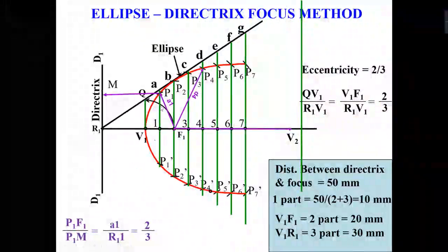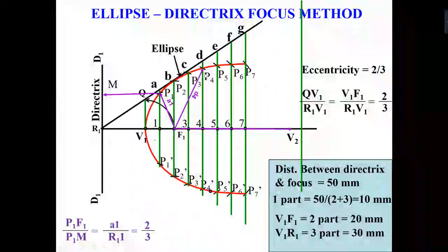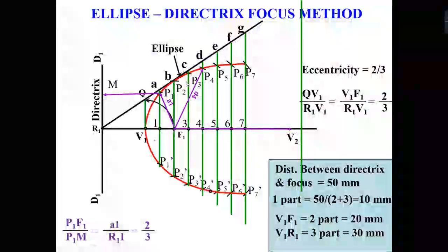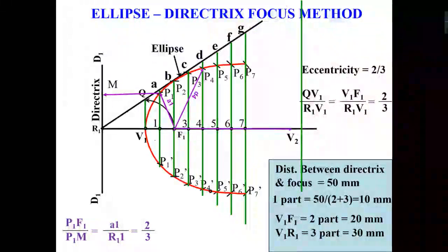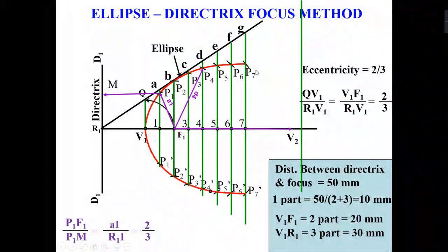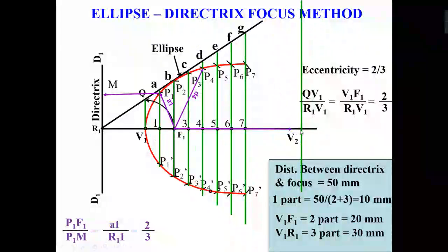When you're using the French curve, you cannot have all the points at once. Only 3 to 4 points will be on the periphery of the French curve. So in this way you can use the French curves. Then you have to join the other portions as well, so you complete the drawing.